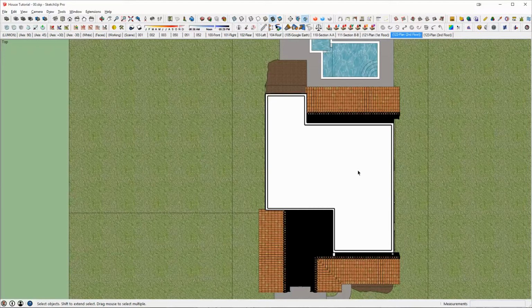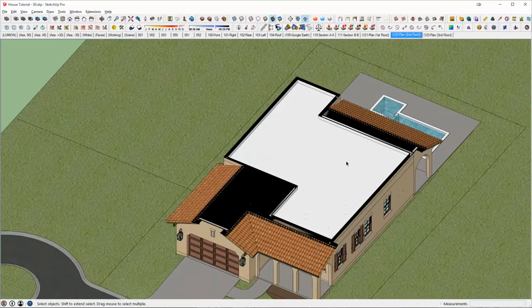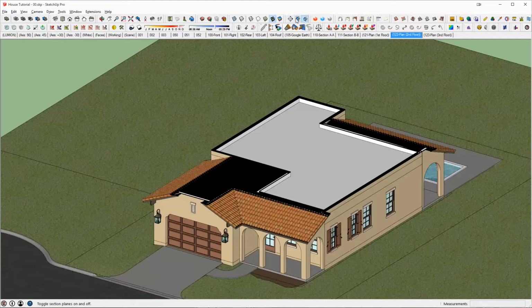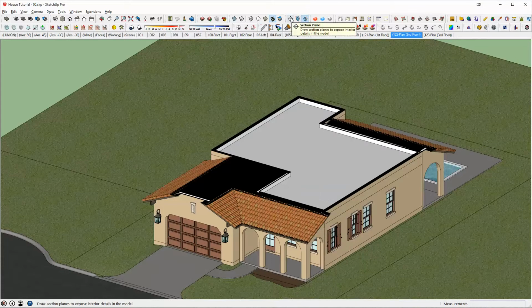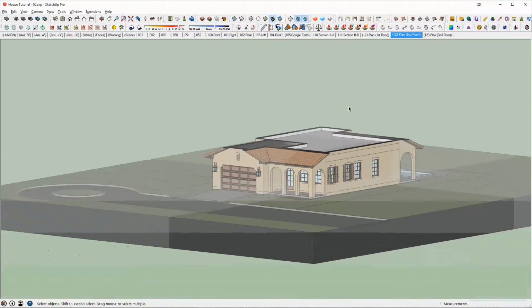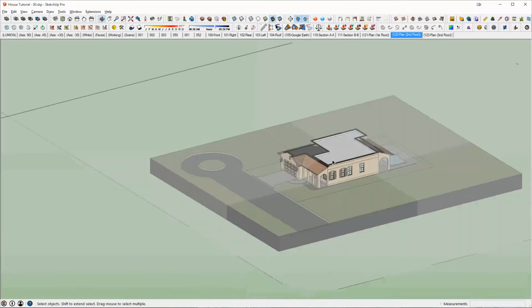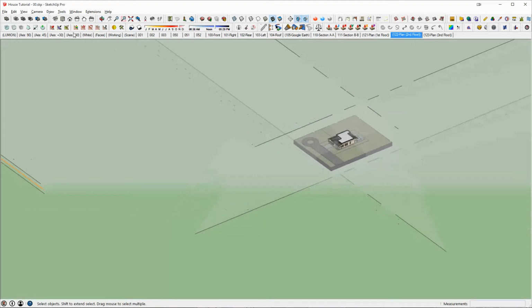And what you're not seeing that's already all set up, which is kind of neat, let me just update this, is that in SketchUp, this panel right here, which would be your section box, this one will draw a section plane, this one displays the section planes, and this one displays the section. Meaning right now this is toggled on, so we're seeing this section. So if I toggle it off, the section goes away.